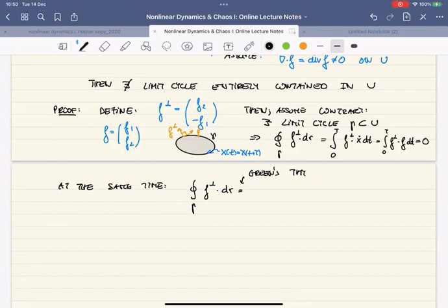It says that you can transform this with the appropriate orientation. If it's clockwise, I think you can transfer this into an area integral over the interior of gamma. What you need to do, but it works out to be Stokes' theorem in the plane, is that you need to take the curl of f perp, which is going to be a vector like vorticity for planar flows, normal to the plane. It will have only one non-zero component, and you take that.